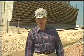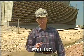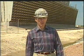As you know, all the equipment involved in these applications requires periodic maintenance. For this reason, we'll now discuss some basic operating problems and how to handle them. Fouling is a common and destructive enemy of heat exchange. A low-velocity flow can start the buildup of deposits on internal surfaces. These deposits can cause changes in temperature and pressure.